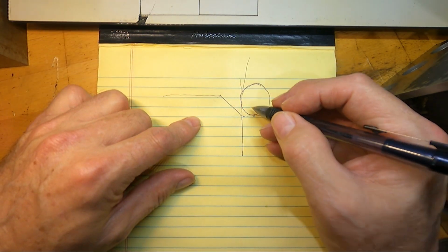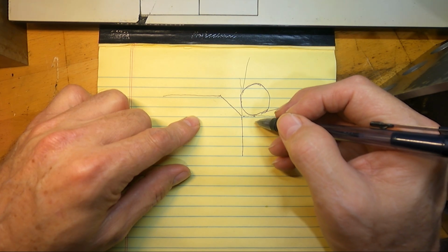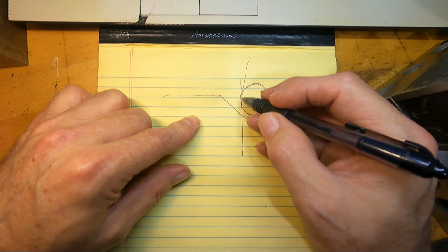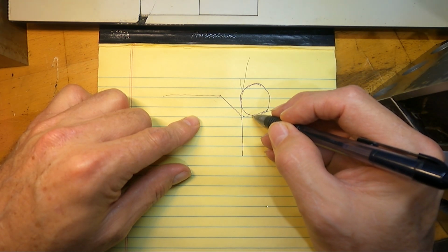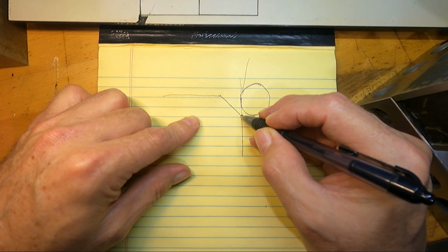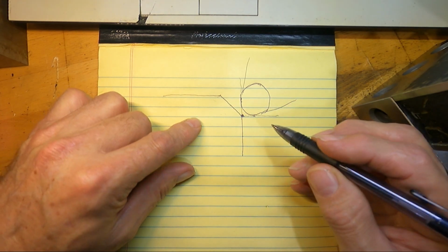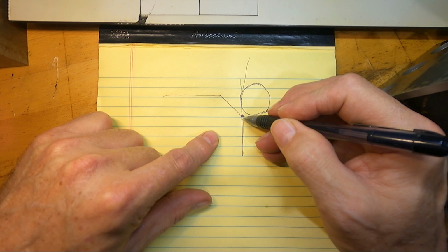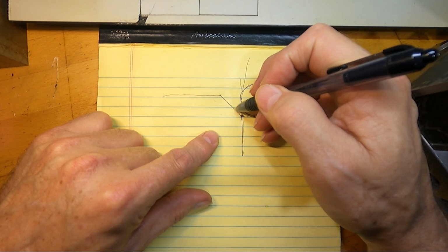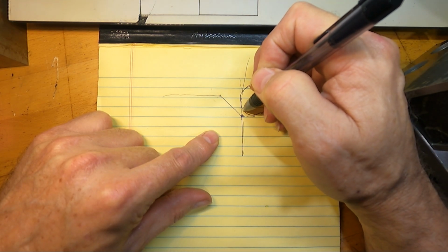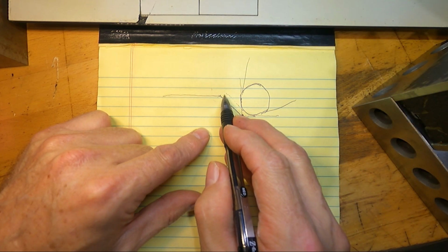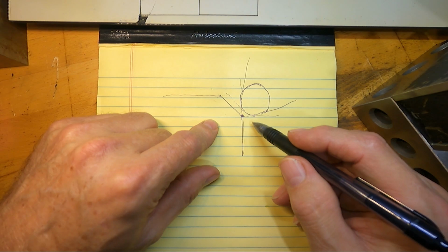If you're doing it on a touch probe, it's the same thing. With a tool setter, you're going to touch this, and it's going to offset that, and you're going to touch this, and it's going to offset these two faces of the insert, which in reality makes that offset of your tool right there. So you can see, if you just program this path manually to the actual shape of the part, we go down here, and the insert would actually be cutting back here until it got up to this diameter, and then it would cut in the right place again.